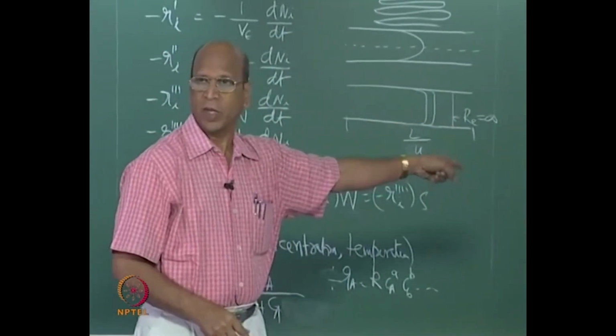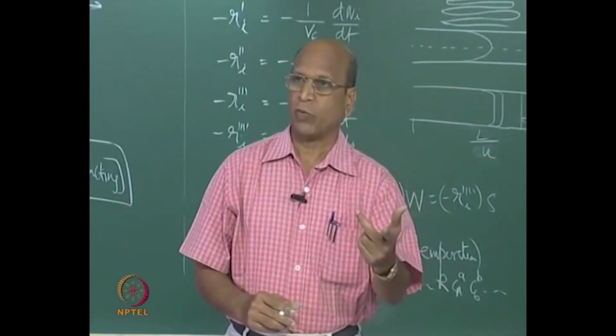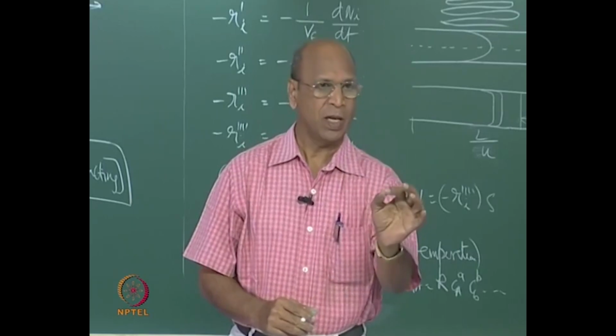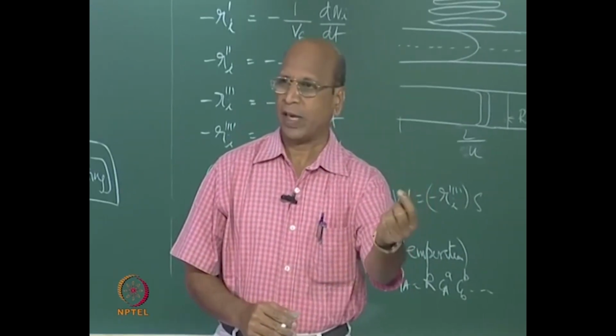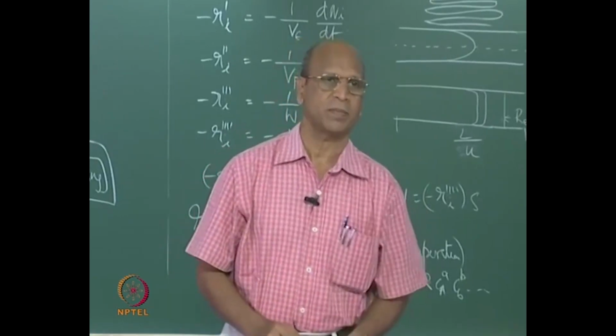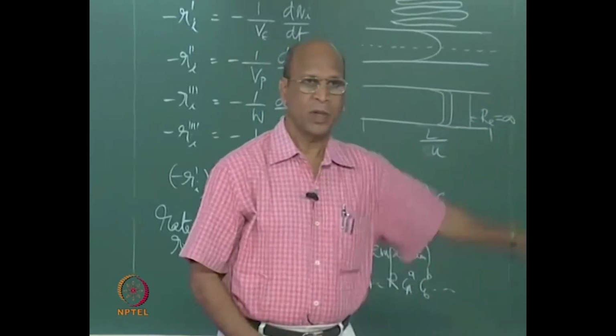Homogeneous only we are talking here when I am talking about these two reactors. So, now at least you have an idea when you choose plug flow. Plug flow is chosen when the reaction times are very small. So, most of the time gas phase reactions will have small residence times required. So, gas phase reactions is one answer, and liquid phase reactions most of the time we conduct in mixed flow.